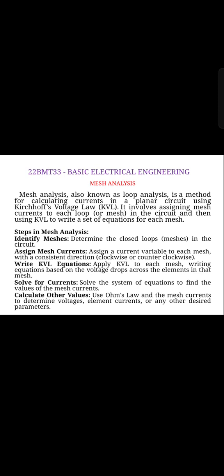What are the steps involved in mesh analysis? First step, identify the number of meshes in a circuit. In the given problem, how many meshes are present? Second step, assign the mesh currents.